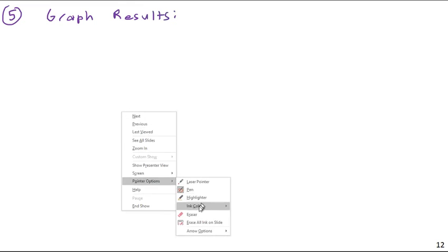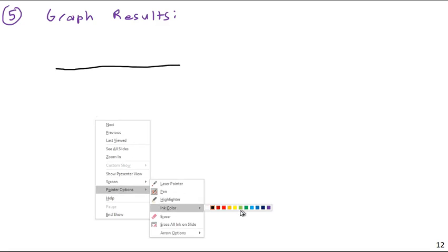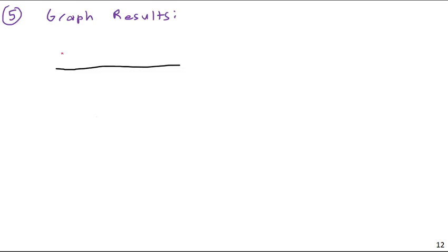So if you're asked for shear and bending moment diagrams, what you're really after is these plots at the end. But you will often need to find the functions in order to create the plots. So graph results. I like to plot these directly above each other if I have space. So that's why, even though I could fit part of it below here, I didn't. I like to plot the load, the shear, and the moment directly above each other if I can, because that makes the geometric relationships between shear, load, and moment very clear. And also in the next lecture, when we learn how to do shear and moment diagrams by inspection, you'll definitely want to plot them above each other.